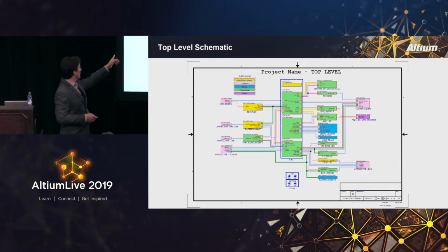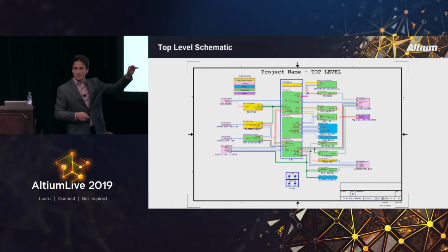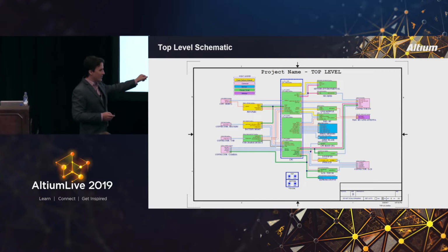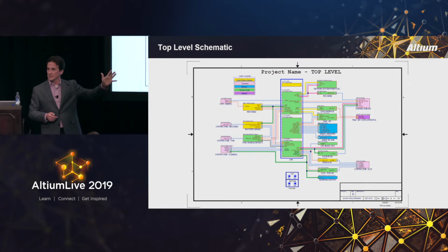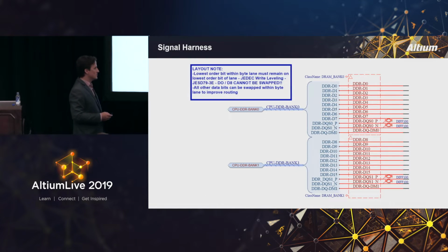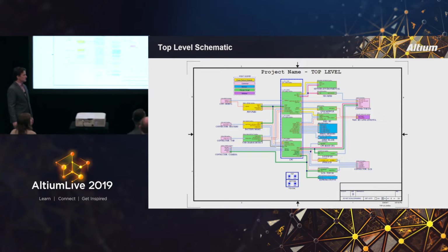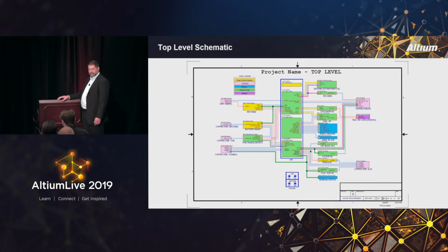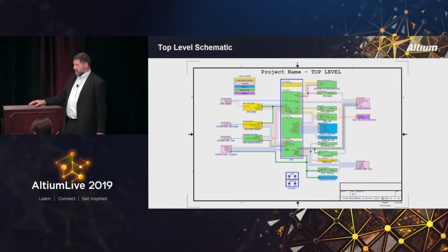And lastly, I have my antennas on a separate schematic as well, identified and called out in the top level. Also, don't forget fiducials and tooling holes. I think that's important to have represented in the schematics as well. And sometimes the PCB part number can be listed on your schematic so that when the BOM is created, they have a part number for the board to order.